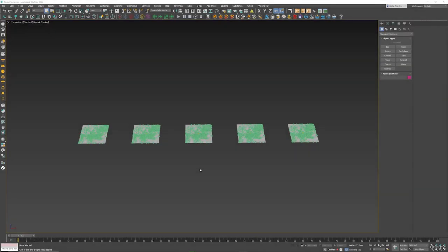The last menu that we will tackle is called Forest Tools, and this is going to give us the power to what is referred to as instantiate. That is going to allow us to take our scattered objects and actually convert them into editable polys, which means we can share that with another colleague who doesn't have Forest Pack.